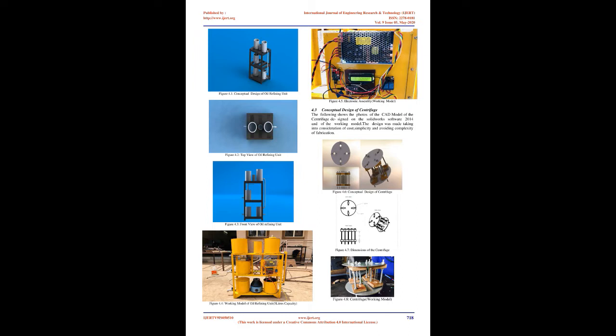The separated base oil was then mixed with kaolinite at a ratio of 1 ml oil to 4 grams kaolinite. The kaolinite was added to remove the dark color and the smell which result from oxidation of some components in the oil. This was achieved by heating to a temperature slightly higher than 250°C, followed by centrifugation for 30 minutes. This process produced a yellow clear base oil and an amount of sludge very close to the initial weight of the kaolinite used plus 5 wt%.